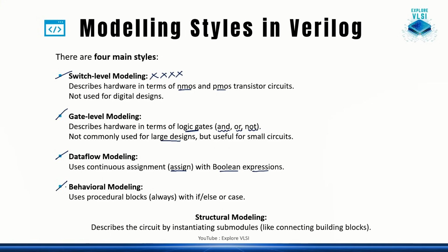In behavioral modeling, we use the always statement, if else and case constructs of Verilog, where we use multiple complex or advanced constructs and write complex designs. So nowadays behavioral modeling and dataflow modeling are utilized. 90% of the code will be with behavioral modeling, and for some statements where it is much required, we will use dataflow modeling.